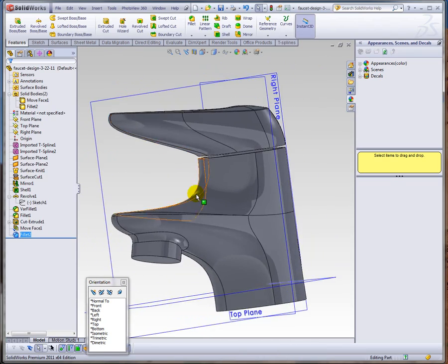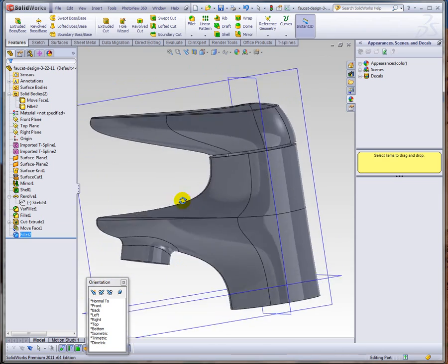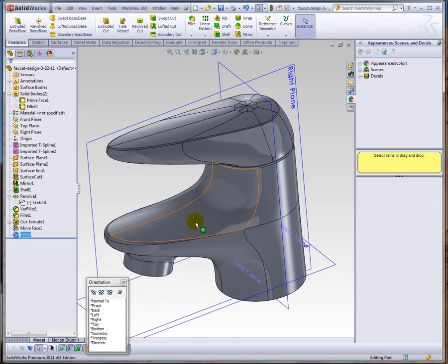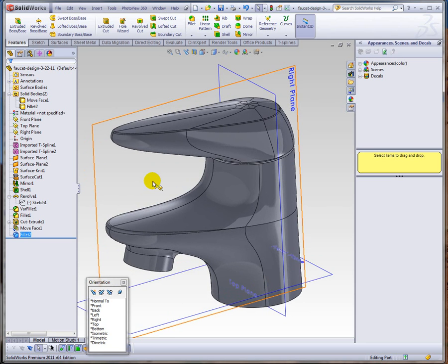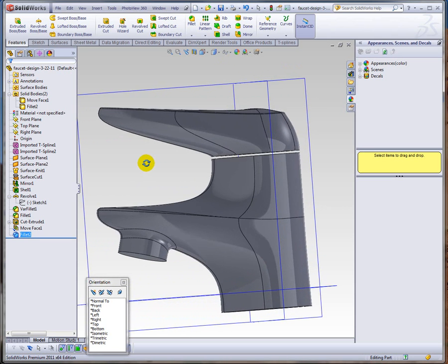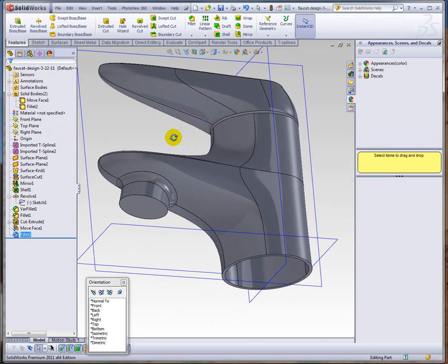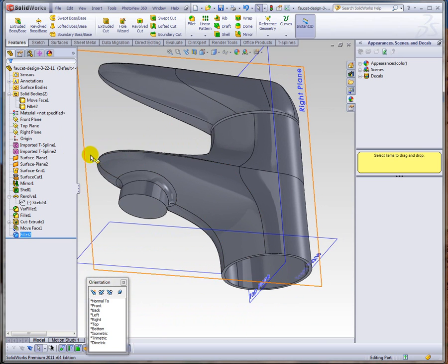So what if something needs to change here, given some engineering parameters? We can do that with our T-Spline features that are directly in here. But one other thing I want to do here, just use the power of SolidWorks. That shell, we did that before this revolve feature and the fillet, after the shell.